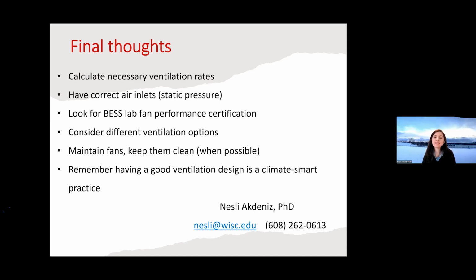Yes, so fan size really depends. I showed a couple of examples and I said it depends on the height of the barn. If they can reach out to me, I can provide them some guidelines. But we don't have a formula that fits any kind of condition. If we have circulation fans, then the ventilation rate requirements will go down. If it is a high ceiling, then it will go down. If it is a false ceiling, then it will go low. So it really depends on those conditions.